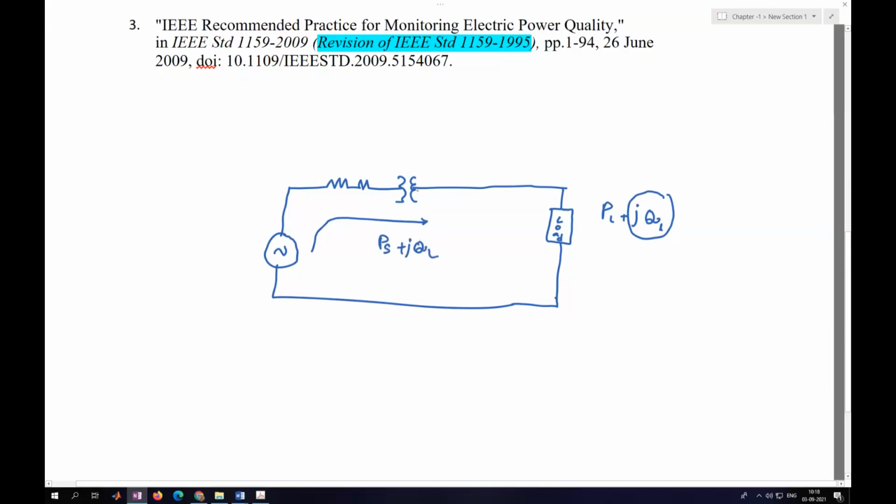going to supply. At this moment, what happened was, the reactive power is not at all useful power on this particular transformer, and because of this feeder impedance, because of the power which is flowing from the source, PS as well as QS, there is a dip over here in this particular voltage. I just mentioned it as the VT. Because of that, the distribution transformer needs to change the tap settings on this particular transformer.